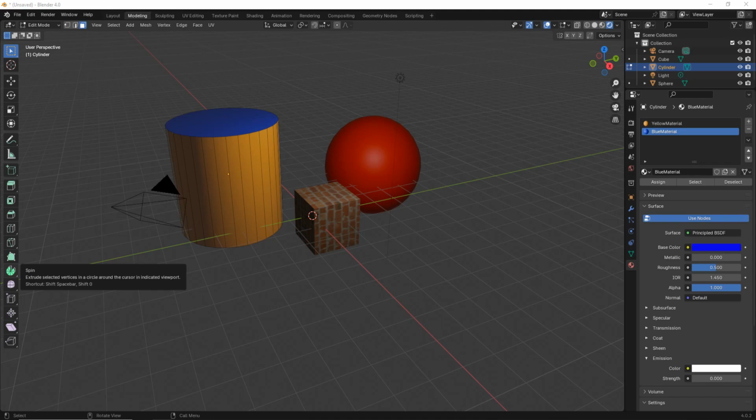The mesh itself from the cylinder now knows to put material slot 0 on the sides and material slot 1 on the top. This will actually cause you no issues at all doing this in Blender, but if you export your 3D model that has multiple materials assigned to it, you should check if the software that you plan to import it on actually supports multi-materials.